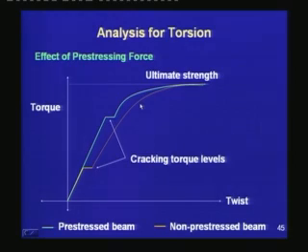Either of the steel, the longitudinal or the transverse, can yield first depending upon their amount, and then the other steel will yield, and finally the beam will attain its ultimate strength. Whether the steel will yield first or the concrete will reach its ultimate capacity depends on the design. If it is an under reinforced section properly designed, then the steel will yield before the concrete crushes.